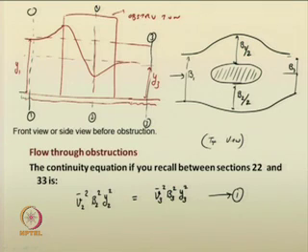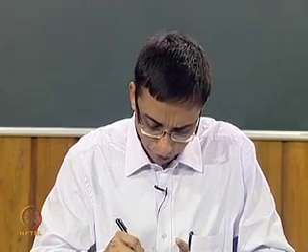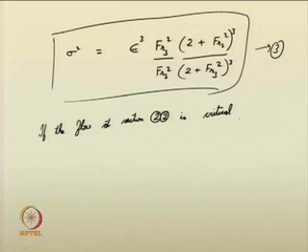The flow in the upstream section is subcritical, and we do not know what the type of flow is in the obstruction, and at the downstream condition also. So, let us assume that the incoming flow is subcritical. So, what we can suggest is, if the flow at section 2 is critical, that means your Fr2 squared is equal to 1, or